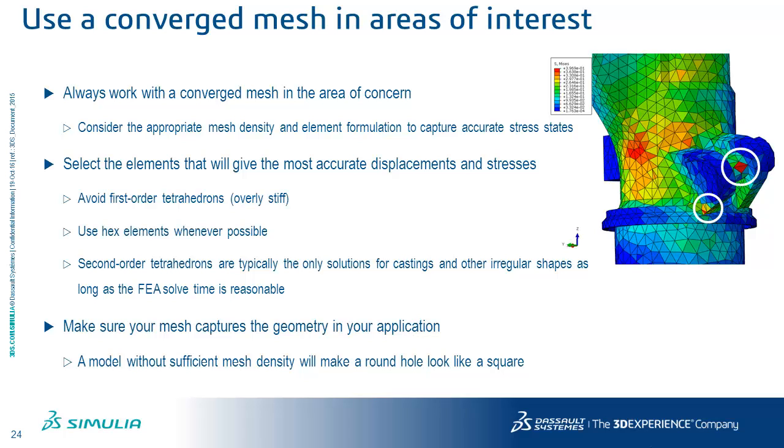Okay, and whenever you are doing the fatigue calculation, we recommend you to use the convergent mesh, so that you have already gone through the mesh convergence study.